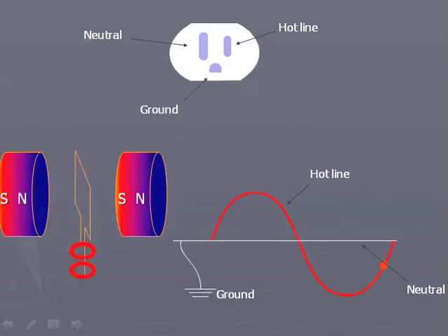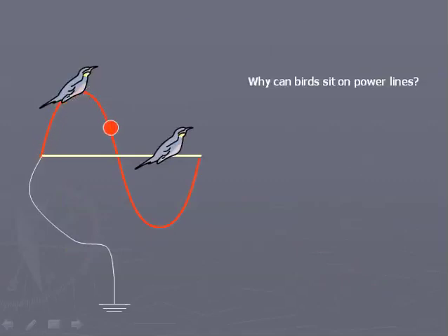The ground is just that, the earth, and is frequently called earth ground. The ground connection in the wall outlet is connected by a very thick wire to all of the other ground connections in the building and is usually connected to water pipes that go down into the ground underneath the building. It is worth noting that the neutral connection is frequently connected to the ground connection at the wall socket, but not always. Slide 40. Let's consider some of the basics of our AC power.